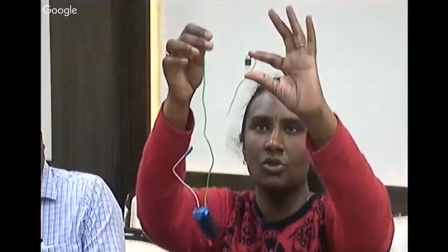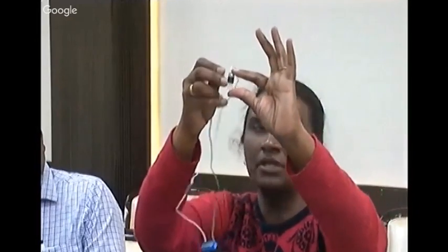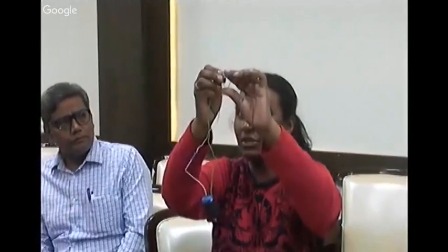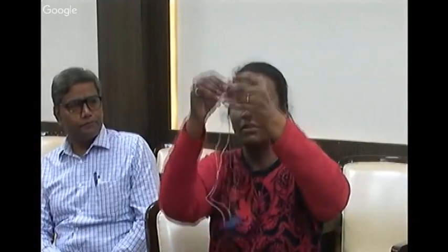Okay, so anode I have connected at the top, and towards my left I have the gate circuit, and towards my right I have my cathode. Now this green one is the cathode, like the negative terminal. Positive is this white. So white I have already connected. This green I am connecting to my left side. Okay, I've made my thyristor forward bias. Is it? I have made it forward bias.